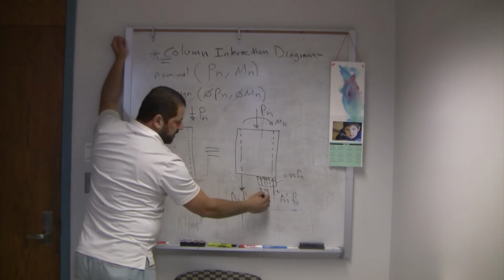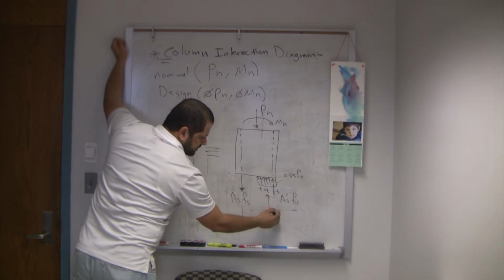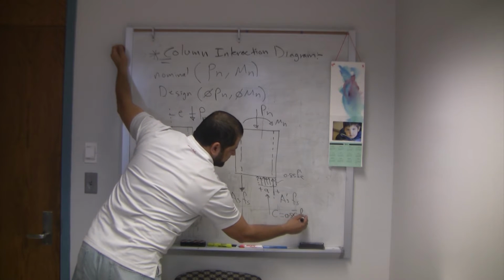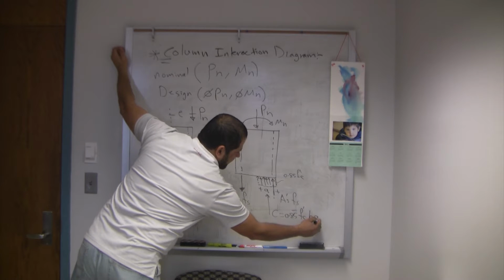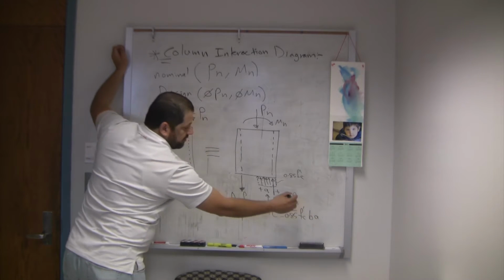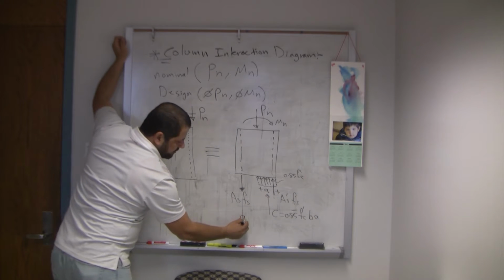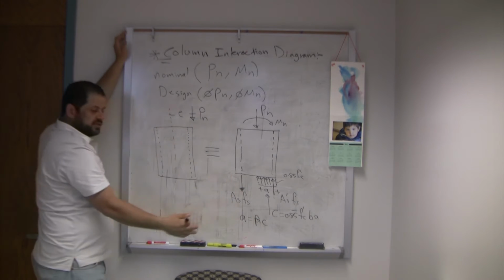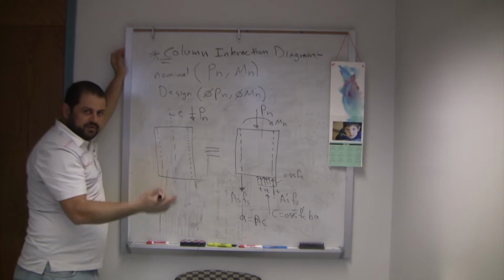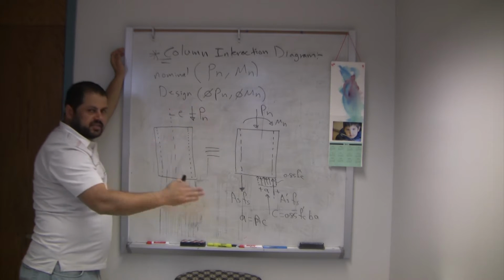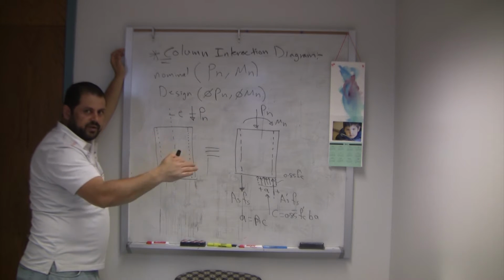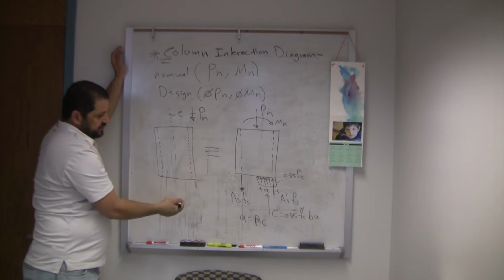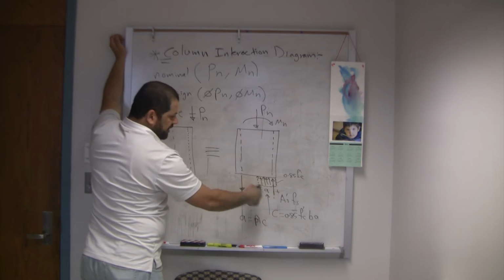This will give you C from the concrete equal to 0.85 f'c b a, and a equals beta 1 c, as before in the beam. Beta 1 c, and beta 1 equals 0.85 if f'c is less than 4 ksi, or decreases by 0.05 for every 1 ksi increase in f'c, as we explained before. So look at this. This is what you may have.